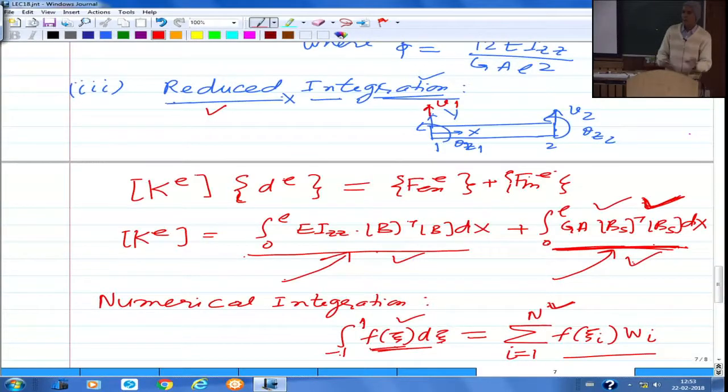When you use this formulation for thin problems, it eliminates shear locking and gives you accurate results. But for thick problems, you are actually underestimating the stiffness, and locking is not there, so your deflections would be over predicted because the stiffness is reduced.